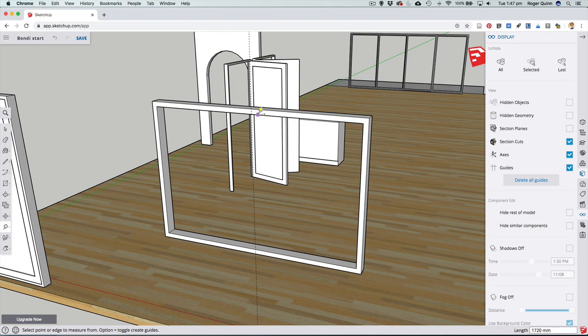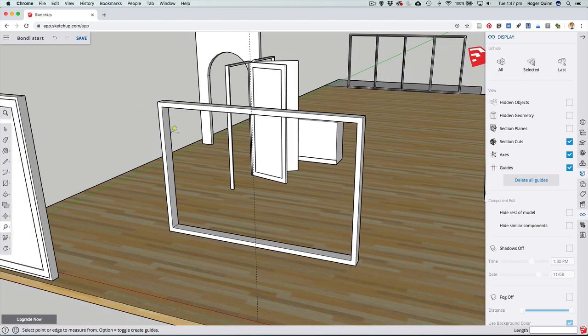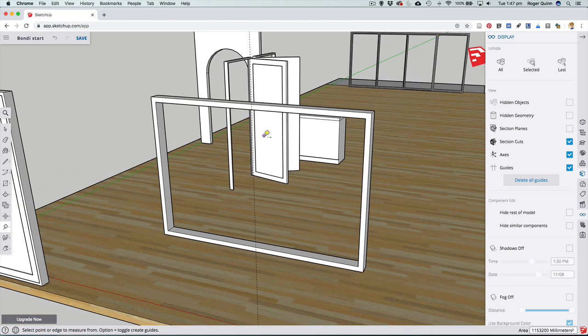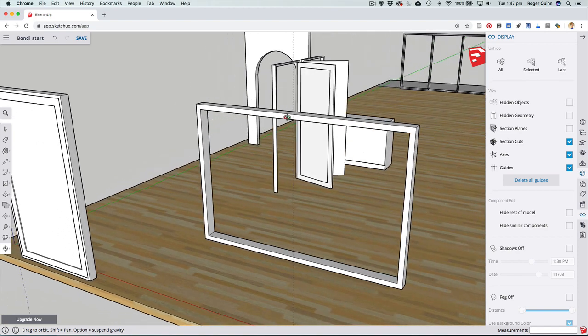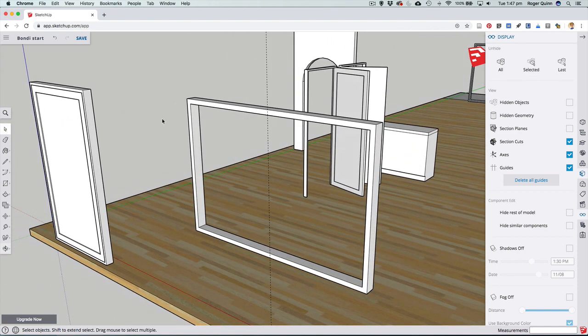It's got inferencing built in, so any time it's got geometry, like an edge and an edge, and you drag along, it will actually tell you where the middle of those two points is. But otherwise, you can do the / thing. Whichever method you use, that will give you the middle, and there is our middle point. So now, and again just confirming I have already grouped this, so whatever I draw now won't interrupt that geometry, I'll draw a new rectangle across that span there, which is exactly halfway. So this is going to make the internal frame of my window.